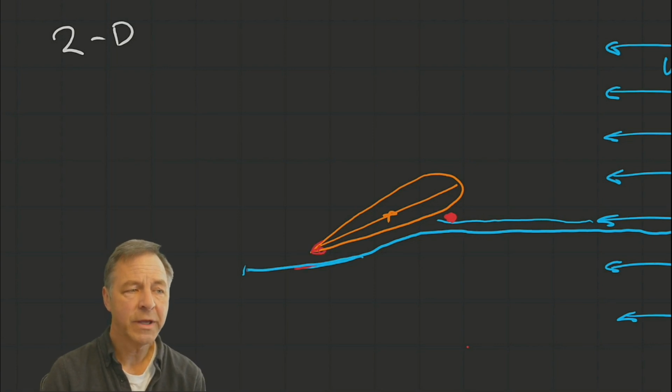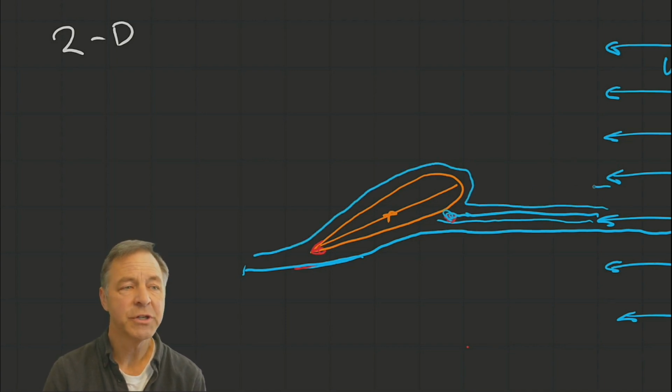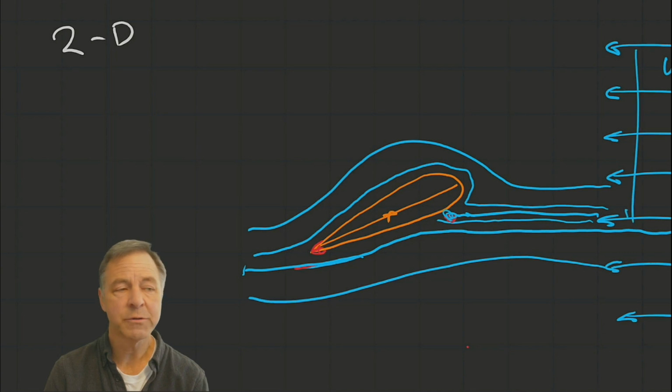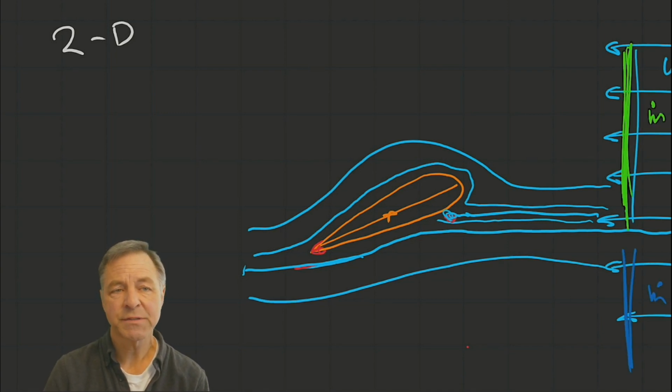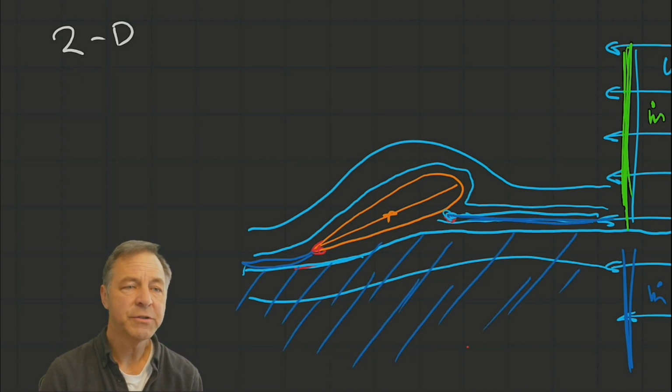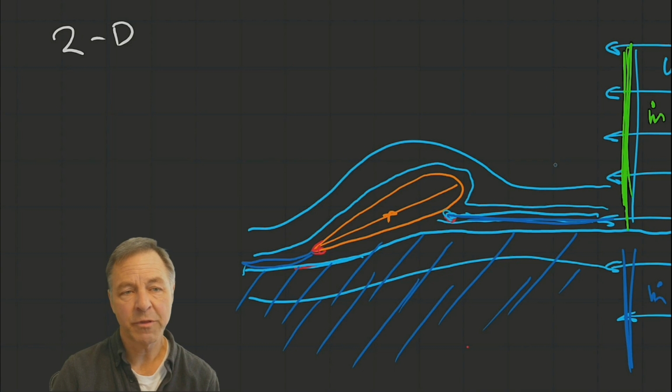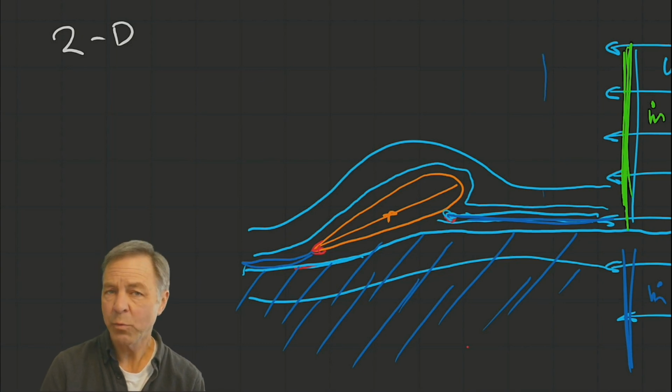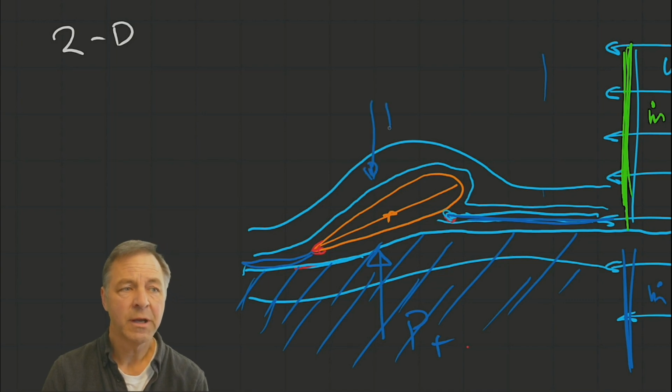They're at the wing trailing edge tip, the sharp pointy bit. They're at the stagnation point somewhere on the leading edge, and the air has to flow around those points. And if we looked at the same mass flow above and below, then things change quite a bit. If you just take the center streamline where the mass flow is equal, you see that that wing being there has deflected the mass flow downwards because of the shape of the streamlines around it.